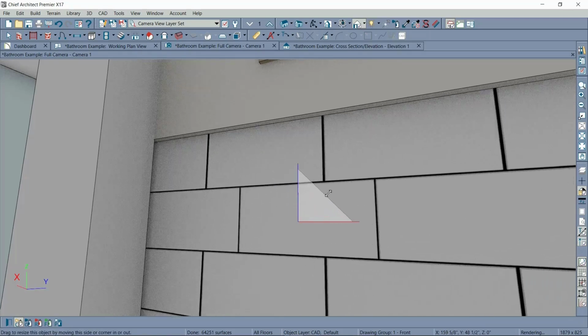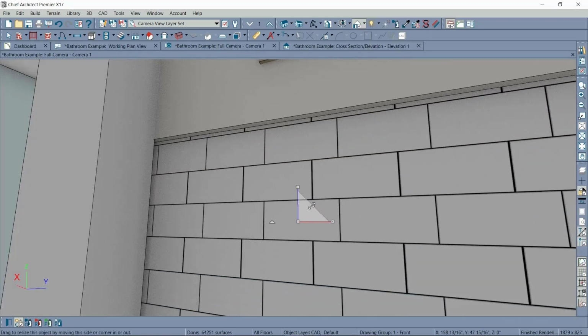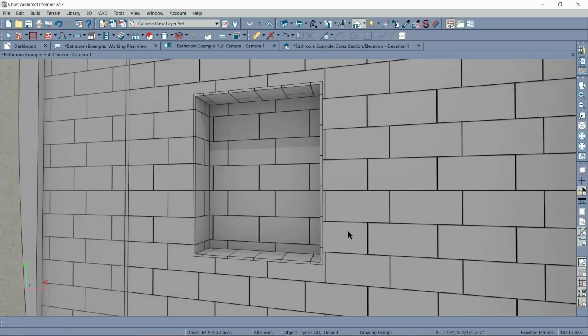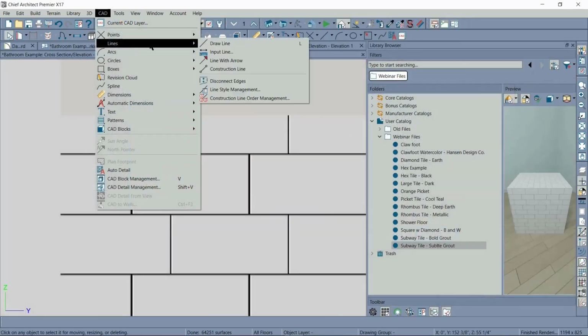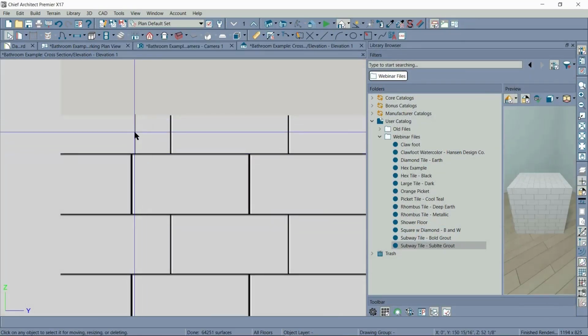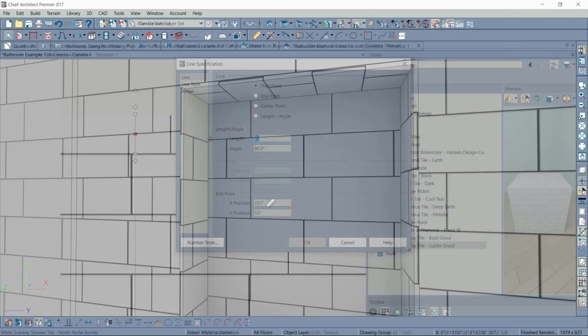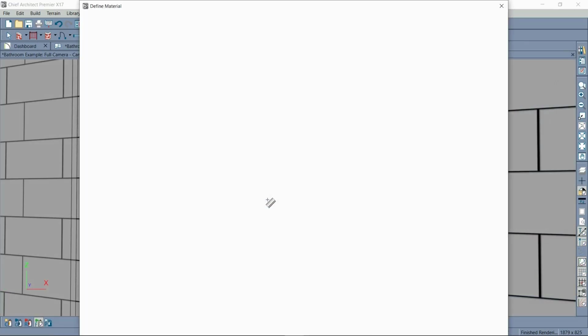Let's knock out a couple examples, and then we'll get to the Q&A, okay? The classic wall niche. We're going to use this tool. Before, we'd have to make a bunch of copies of the plan material, and we'd have to measure them in an elevation view to see where we wanted to put them, and then we'd have to move them individually with the Adjust Materials dialog. I mean, we've done it before.